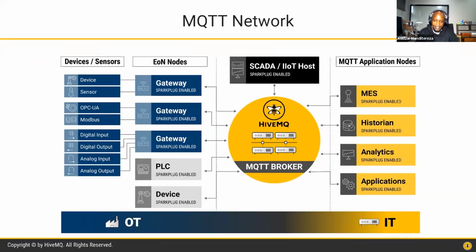So all applications, which could be a PLC or SCADA system at the factory floor, or an analytics application in the cloud, are called clients, and they have the capability to send and receive messages through the broker. When a client is sending a message, it is called a publisher, and when it receives a message, it is called a subscriber.